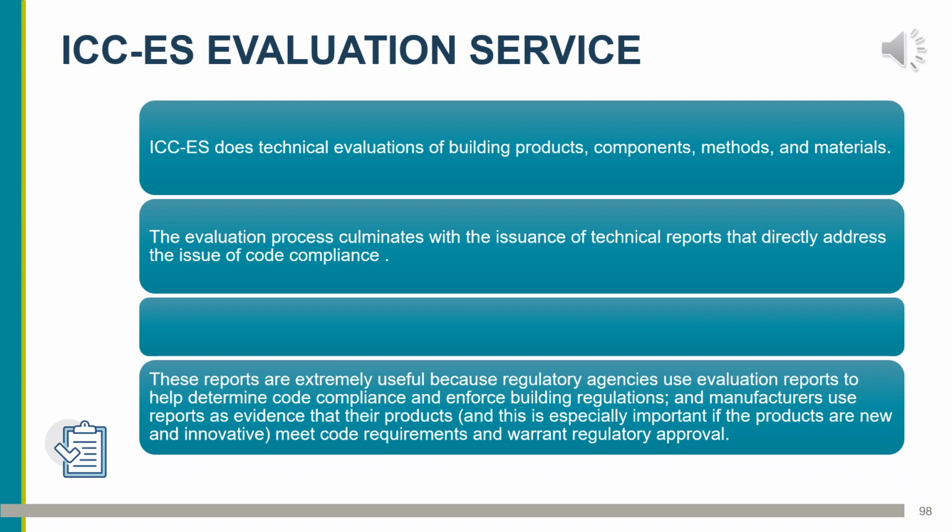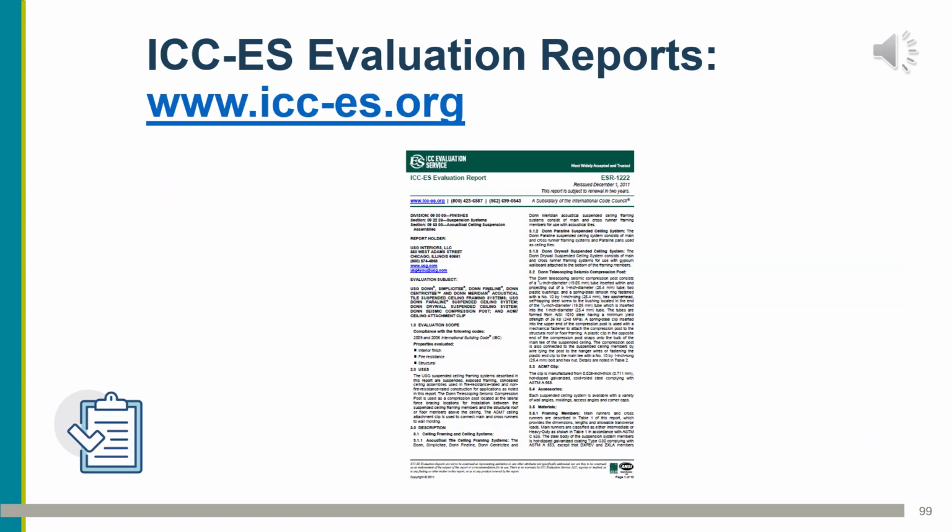There are different evaluation services, and again, many of these are approved for use. ICC has the ESR reports, which I highly recommend. I find that they're very helpful. If you have an iPad or even a phone out in the field, you can look these up very quickly. And quite often, the ESR report is going to be very helpful to you. I have provided this ICC evaluation report for the ESR reports, and here's the website.